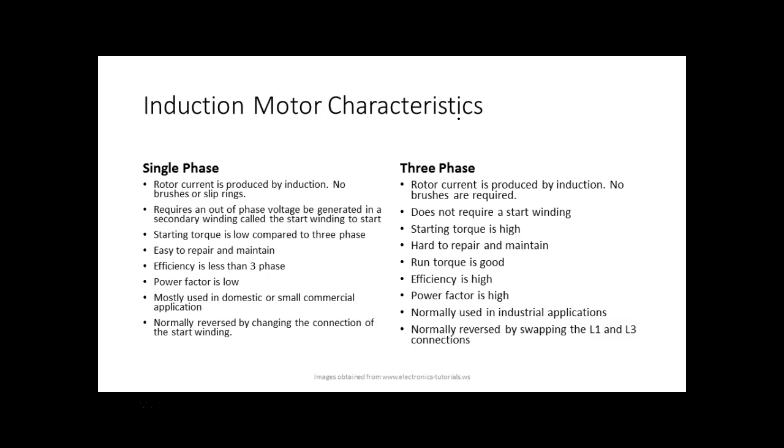If we put AC into that coil of wire, it creates a changing magnetic field that has motion. If we get two coils close together, the changing magnetic field in one will induce a voltage into the second. And that's what we call induction. So induction means you induce the voltage into a second thing from the first, right?